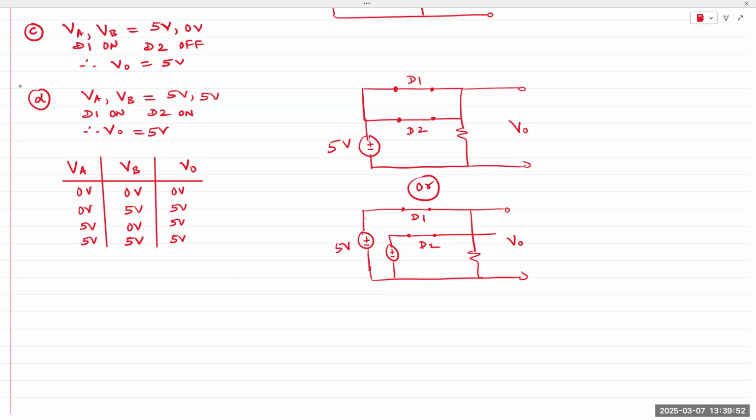Real life circuits obviously do require 0.6, 0.7 volts to turn on, like diodes and transistors, that forward bias drop, and so we need to account for those voltages also. Anything in the middle is undefined, so anything between 0.3 and 3 is undefined. That allows us to keep a gap between the two. Ideally, we would want as small a voltage as possible. Power consumption, that's the main thing, right?